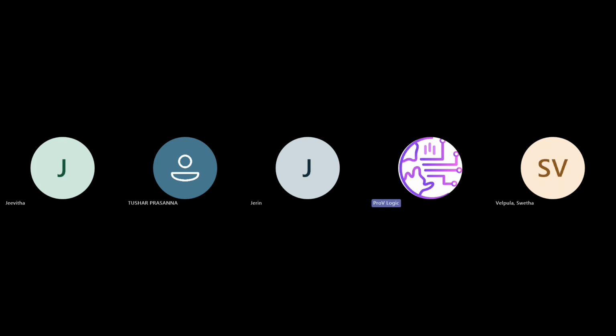Suppose you are verifying 32-bit address and 32-bit data, it is very difficult to generate values for 32-bit, right? 2 power 32 number of values we need to generate directly, manually. But in most cases we don't use all the 2 power 32 values. Why? Because there is no need in practical terms.